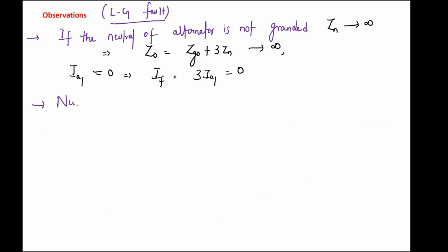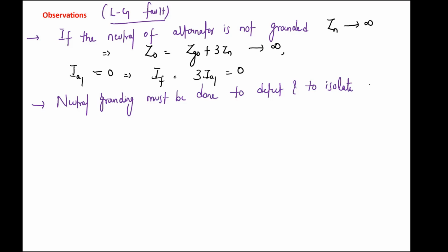So neutral grounding must be done to detect and to isolate LG fault. Not only LG fault, even LLG fault also. Okay. So those are the first two important observations. Next,